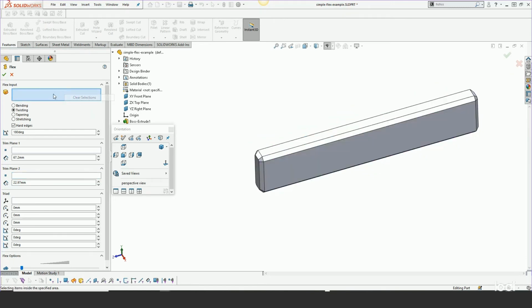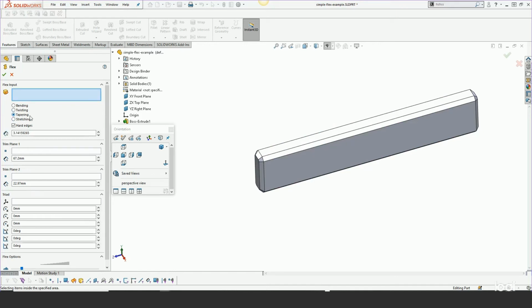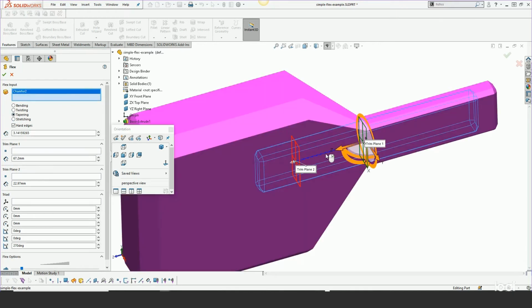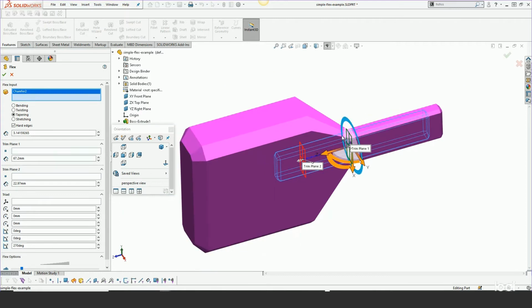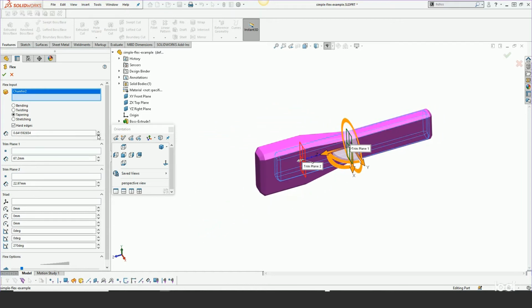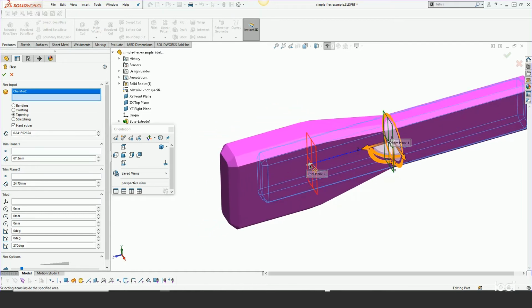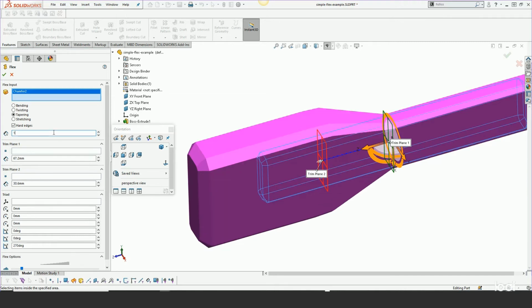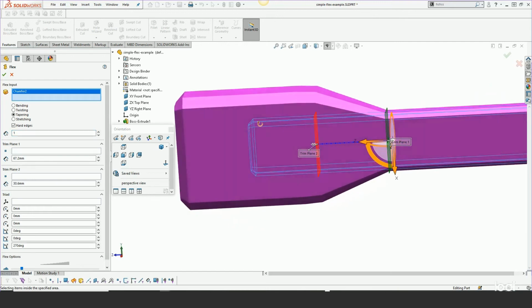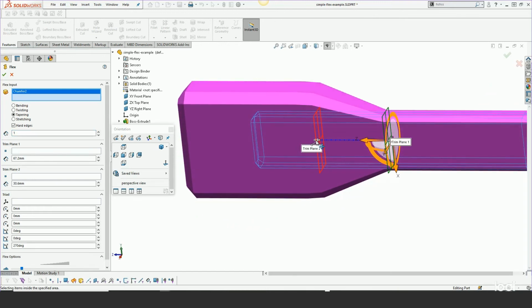Okay, moving on, we have taper. And as you can imagine, with the trim planes that I already have set here, let's just bring this down a bit. What we're doing basically is tapering the model between the trim planes. And we have a value here, or a dimensional offset that we're setting. So we can make it a full 1 millimeter there. And that's what it's doing. It's just tapering down the model in this area.